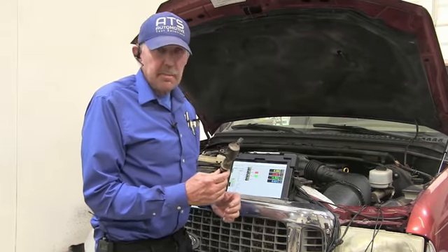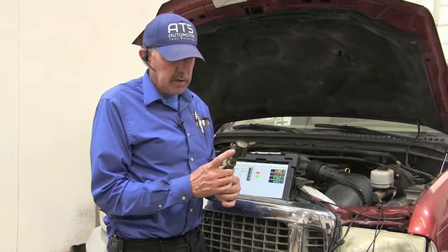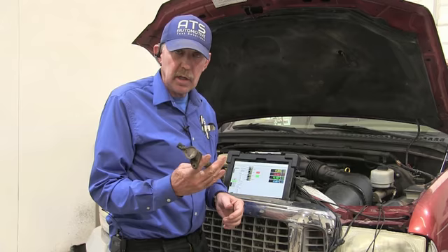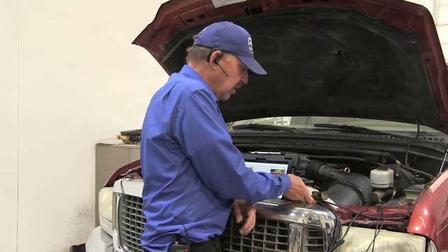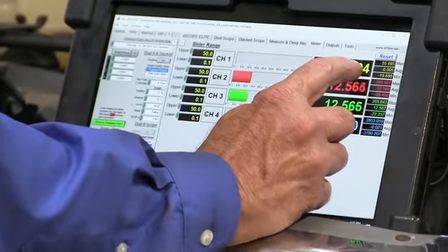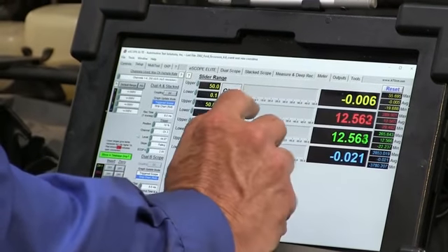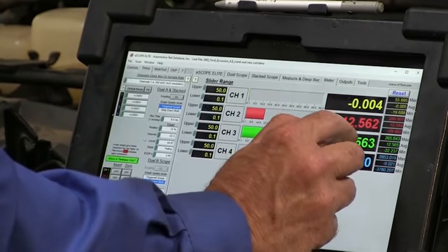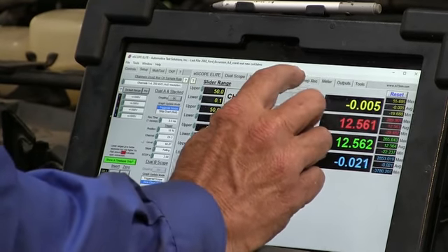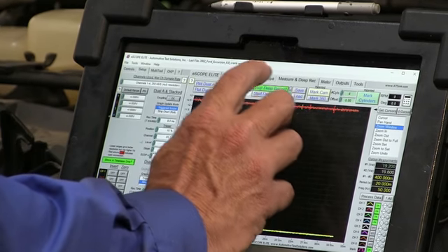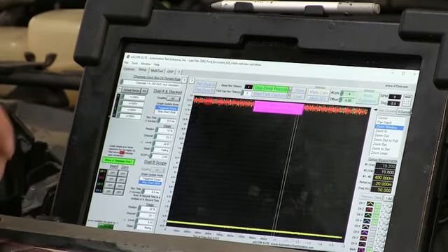Okay guys, the shop has gotten a new Motorcraft spark plug and coil. These are OE components. They've installed a number 9 on this engine now. So channel 1 is on the transmission output speed sensor. This is on number 1 coil. This is on number 9 coil. So what I want to go ahead and do is we want to do the cranking wide open test like we had previously done. Go ahead and crank it wide open.